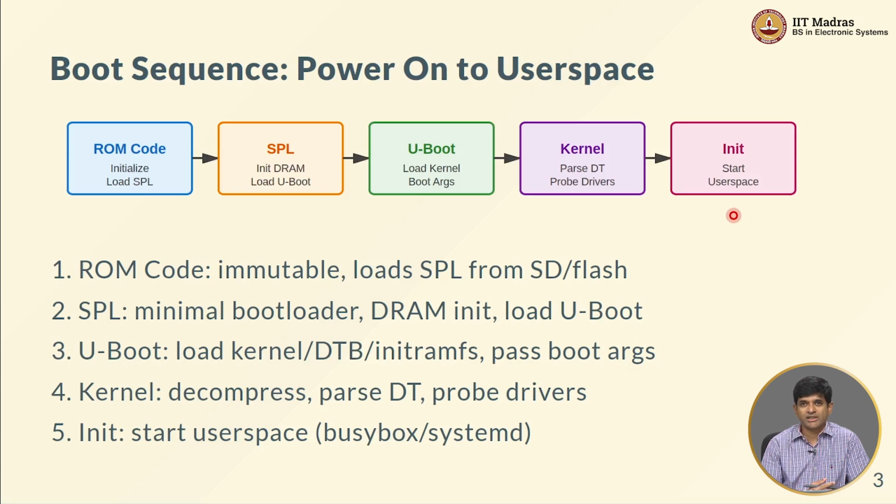Now, combinational logic, when you switch on fresh, doesn't have any particular behavior. It just depends on whatever input it sees, and that's what you're going to see at the output. Sequential logic is different. What sequential logic does is that you have a clock, and only when the clock signal changes does the sequential logic basically update.